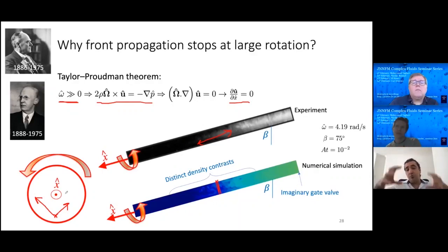Since this is true throughout the cross section, the heavy and light fluid pieces cannot organize themselves to create large structures, large penetration, and large overturning of the interface, or a bypassing of the fluids in the transverse direction. So this is another crude way of explaining why the interpenetration stops.